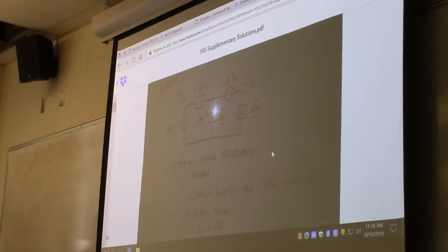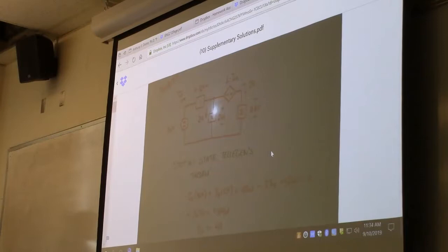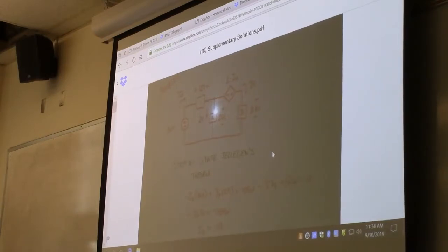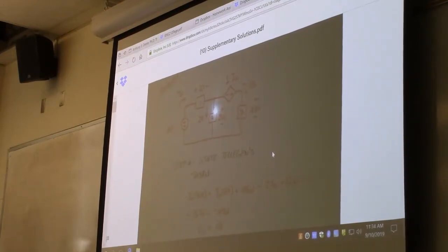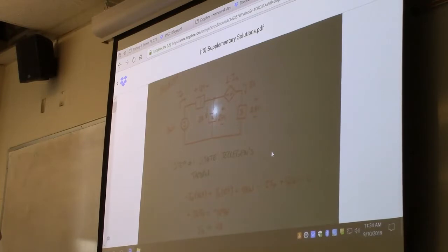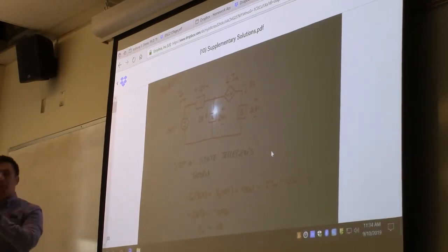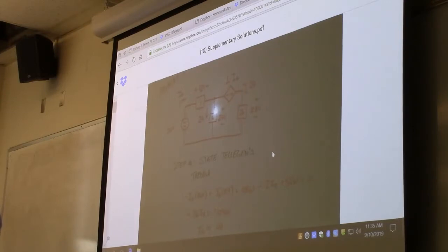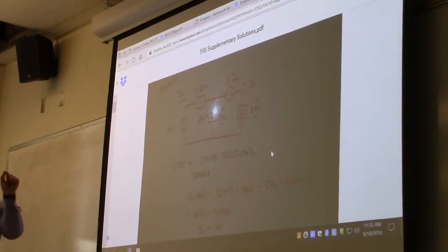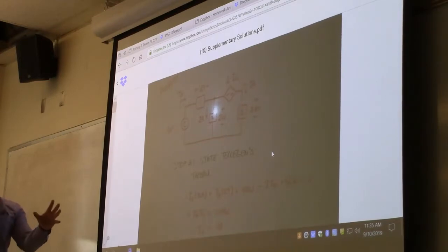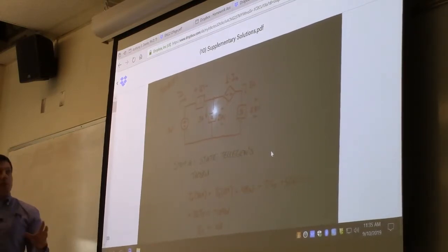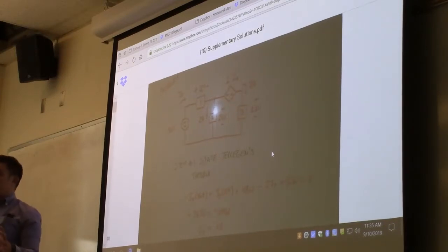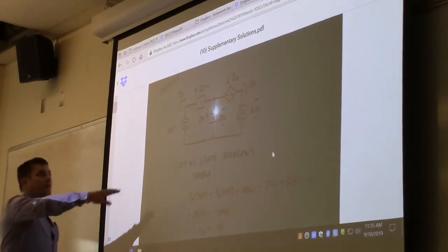Yeah, because the Ix on the left side is traveling the same direction. That is the thing that trips a lot of people up. That's not the reason. So let's look at the voltage and the current independently. What is the voltage across the terminals? It's 1 times Ix. Take that value, set it to the side. What is the current flowing through it? It's 2 amps, but it's flowing in the opposite direction of the passive sign convention, right? It's flowing from the negative to the positive terminal. So that's the reason why there's -2. It has nothing to do with the direction of this over here.